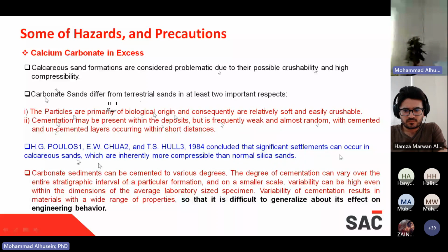Now, some consultant today says, okay, we got dense to medium dense, and sometimes very dense sandy soil. So we can get a bearing capacity of, for example, 100 kilopascal, and we can build our superstructure, and we don't need more than 100 kilopascal, ignoring the presence of these materials, even reaching maybe 90%, and saying, no, it's okay, no issue about this. After certain years, not even reaching 5 years, the foundation failed to support the structure, and the structure in general failed to stand up.